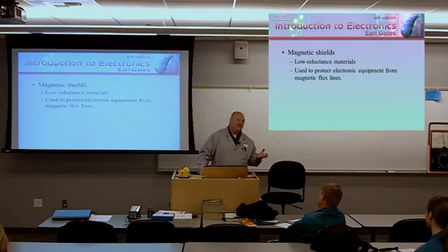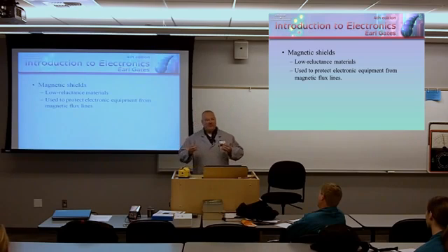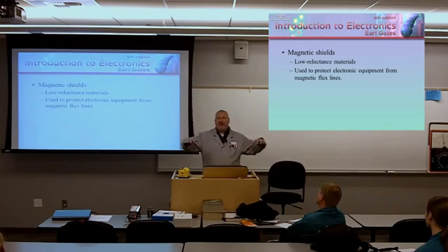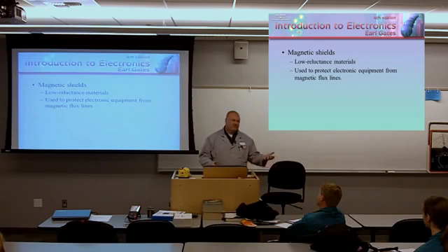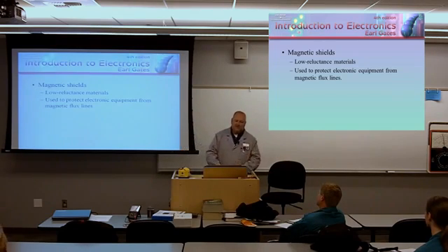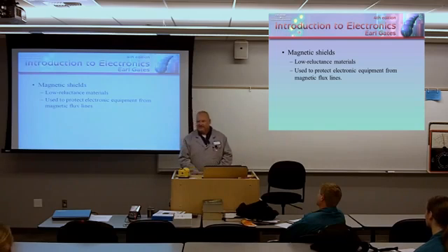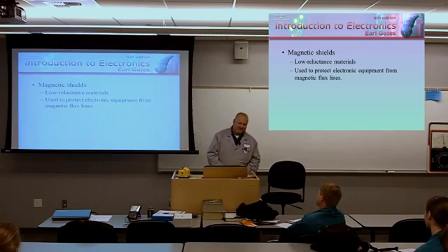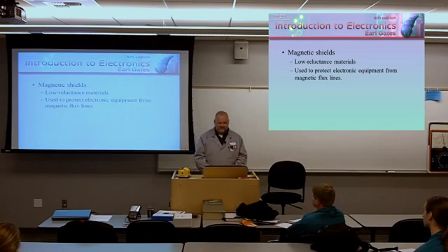So what Boeing actually started doing is putting a conductive layer into the composites, which will allow current from a lightning strike a place to dissipate. So kind of get rid of the aluminum only to put a conductor back into the composite. It's still highly efficient and lighter and stronger and everything else. I guess lighter and stronger. I don't know. When they fail, they fail big. But I guess when aluminum fails, it fails big too. So I don't know. I like kicking it old school.